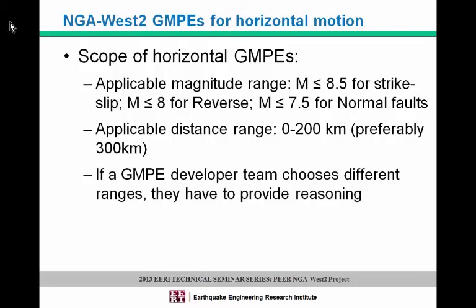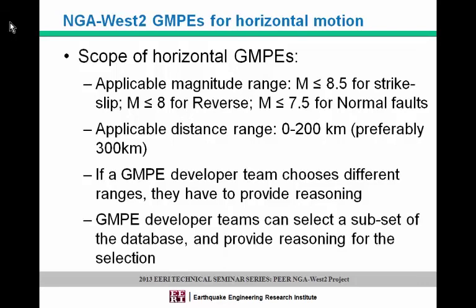We don't want to miss the main shock. We didn't include aftershocks. A couple of other GMPEs said, no, we can use aftershocks, especially for site response, even though the magnitude scaling and other things are different. They used it. We left it to their expert judgment, but they have to justify, exactly as I mentioned. That was one example, and there are other examples.